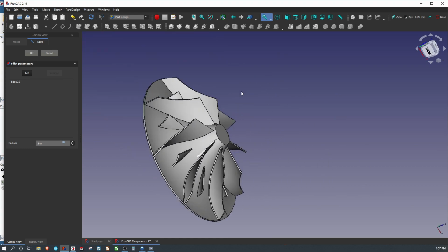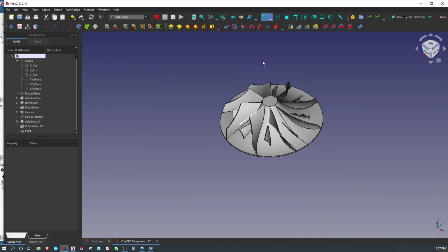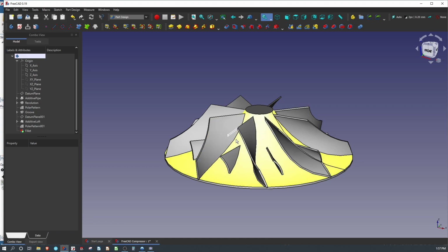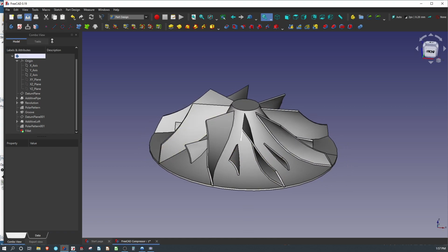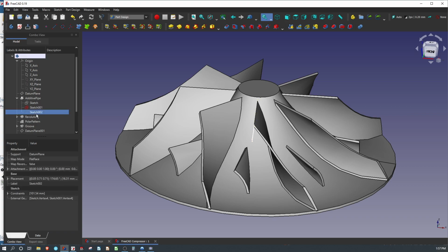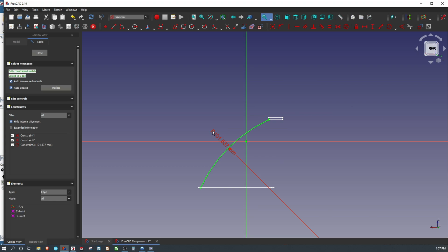At any rate, we can have pretty much the same stuff in FreeCAD and DesignSpark, and we've talked about some of the advantages of DesignSpark, but let's talk about one thing in FreeCAD that really does make a big difference. If we go to the additive loft, no, let's go to additive pipe, so we set our definitions here, sketch 002, there it is. Let's say that I want to adjust this to be 150, totally changing my blade profile.